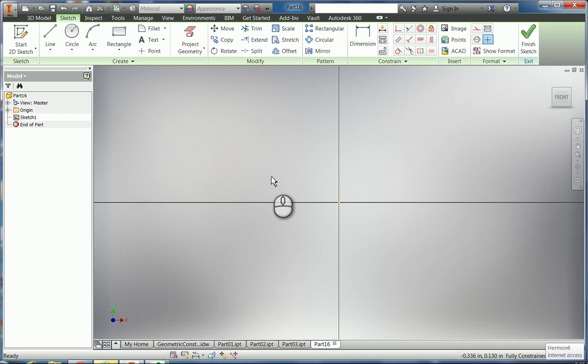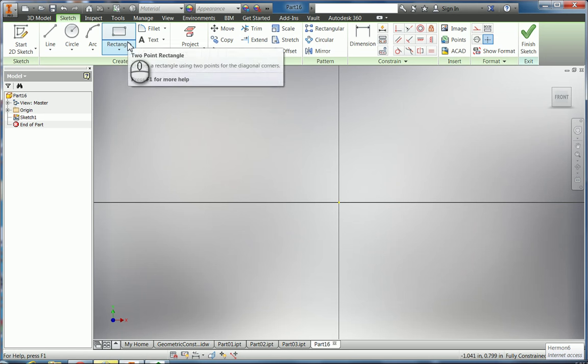Really what we have, if you're looking at your diagram, is a straight horizontal line on the bottom. That's the easiest part. But all three of those next sections are actually curves. So that first section on the left side is a 6 radius curve, and then you have a sharper 0.4 radius curve, and then another 6 radius curve down the back side. So what I want to do is place some points in between the 3 curves where they're at.